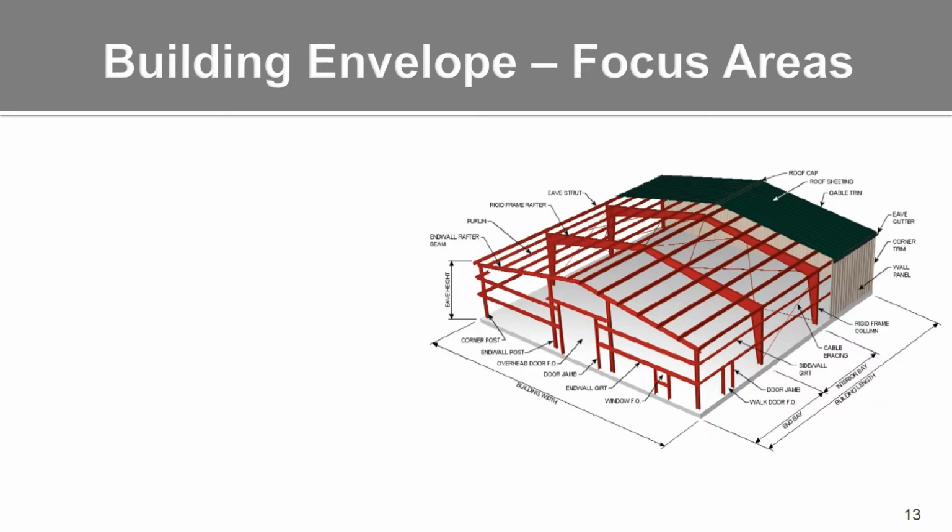And if you have purlins, such as C or Z shaped purlins spaced roughly 5 feet on center, and then you would have insulation that would either be compressed between the metal panel and top of the purlin, or for the walls, you would have insulation either compressed between the metal wall panel and the purlin, or it fills the cavity of the girts, which may or may not be compressed.